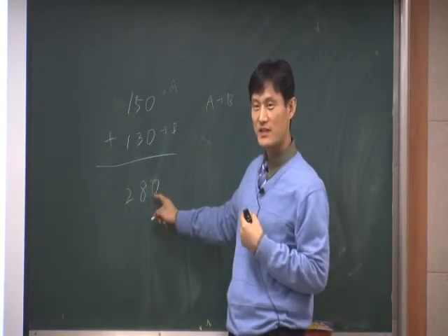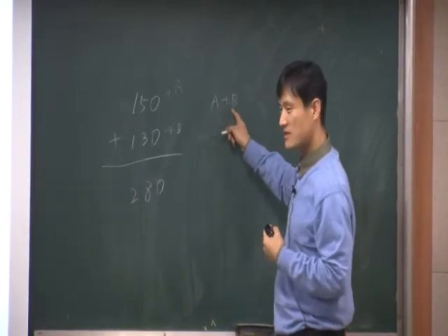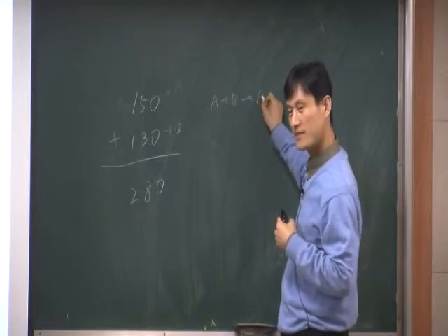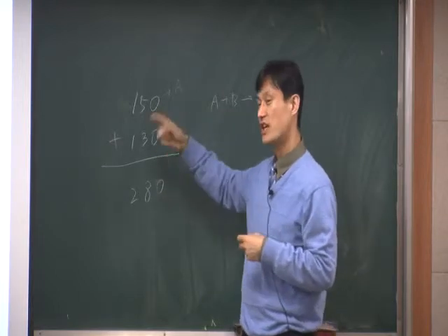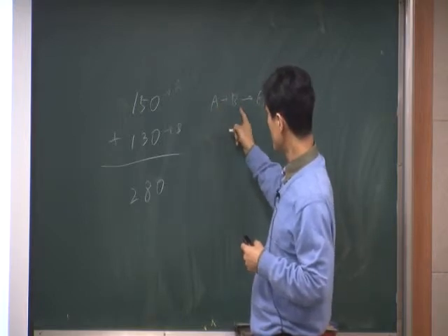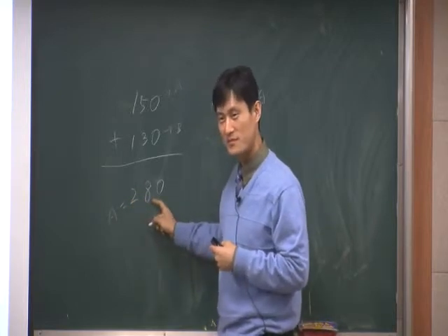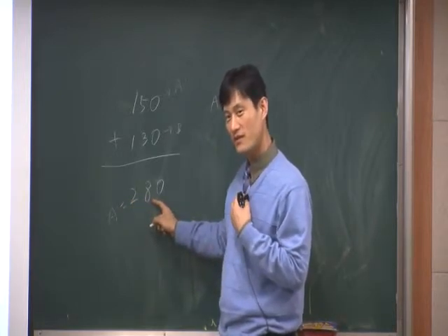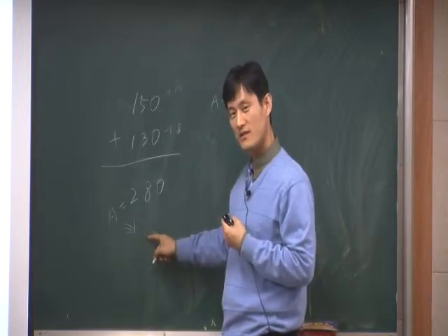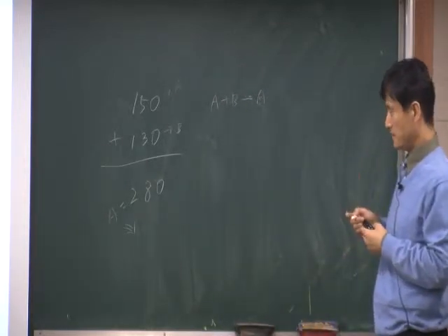I'm expecting this value, right? Typically when you do this in assembly language, when you add these two, the result goes to A. So now the A value is changed. You have A and B with these values, but when you add, the result goes back to A. So I'm expecting A to equal this value. However, if you do this, what value do you actually see? You don't see this value, right? What value do you see? Think about unsigned.